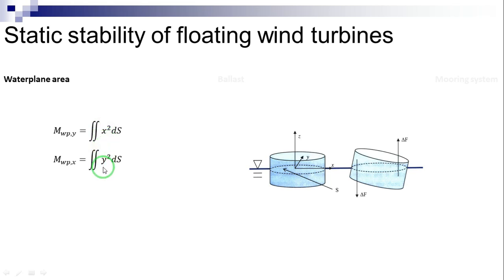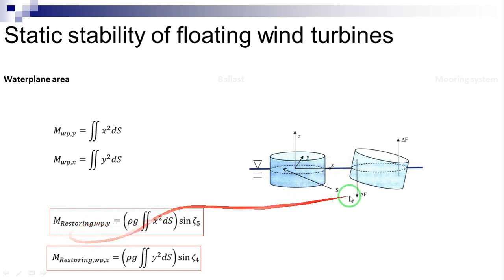The dotted line on the structure in this figure represents the structure's water plane. For small angles of deflection in pitch, the shape of the water plane is relatively constant. When the structure is perturbed in pitch, one side of the structure is submerged and the other side is elevated from the water. The submerged side experiences an increase in buoyant mass and a larger volume of water is displaced on that side.